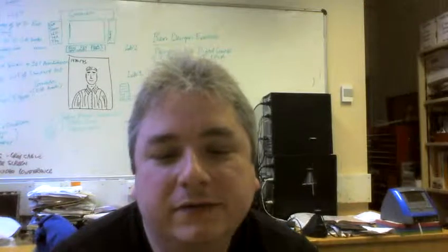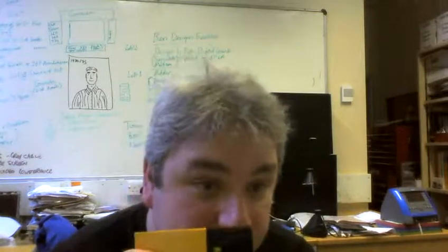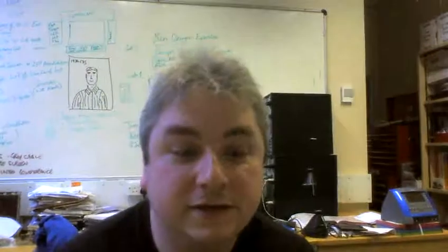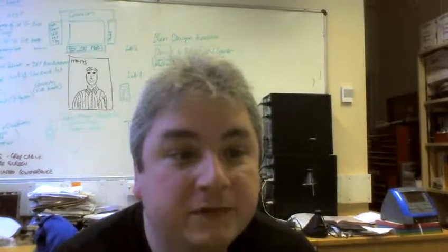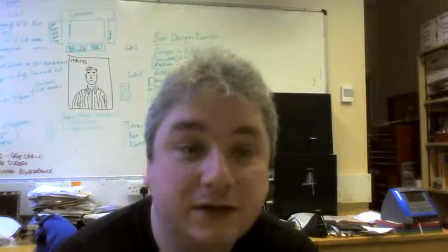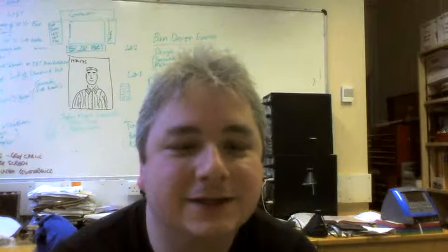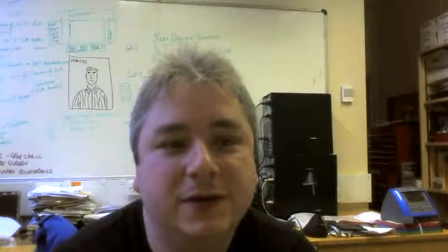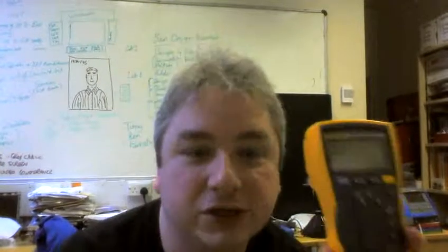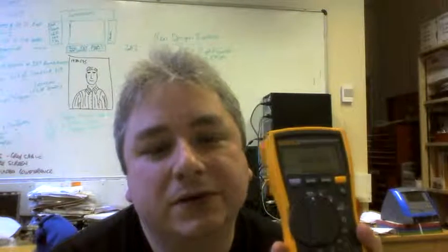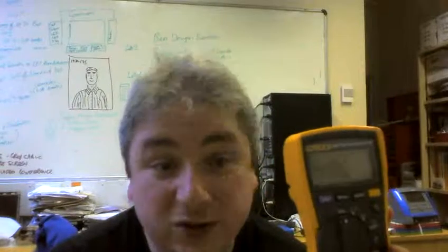And on the back here it says frequency to 50 kilohertz. Now, if you didn't pay too much attention to the front of this multimeter, you'd think, oh right, you can measure AC values up to 50 kilohertz. That's pretty good for a multimeter, and it's a Fluke multimeter. So I thought, well, yeah, why not? Unfortunately, it doesn't, because this frequency value here is the actual frequency range when you measure a frequency. Not measuring frequency in terms of voltage or current, but measuring frequency in terms of hertz. Okay, because this can actually measure frequency.